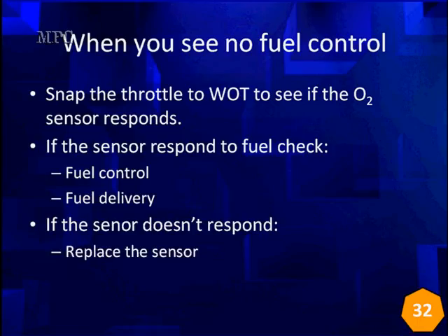Change the sensor. Now, this may seem like a real dumb thing, but we find a lot of people going in the ditch here. If we can't get good fuel control and good delivery, we need to replace it. And we've divided the sensor from the rest of the system by doing this test.